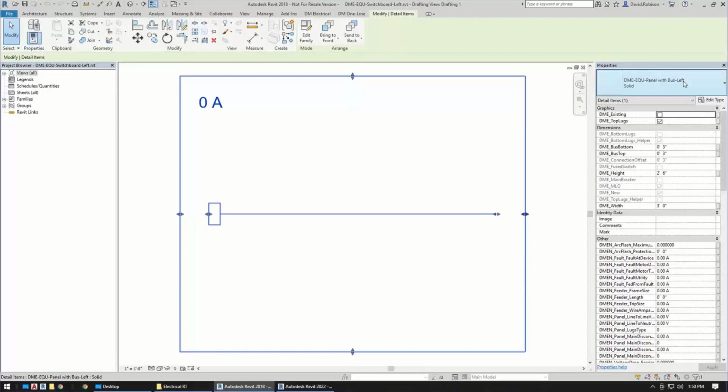So if you're using this family in a bunch of your projects to define where all of your tags go, you don't have to go back and redefine it if you make a change to how the family works. And actually, we don't with ours. A lot of our project files have old versions of our families in them, but those are never used because we pull the latest version of the family from disk rather than from the project. So when you're updating your families, you can just update them on the disk, the family itself. You don't have to go back and update all the projects that use it.